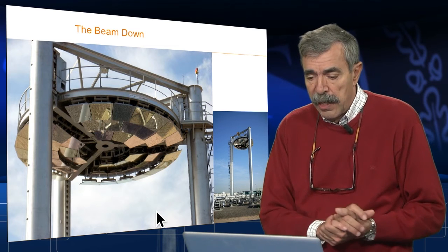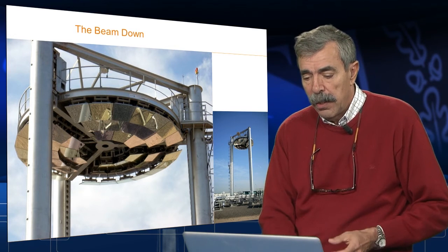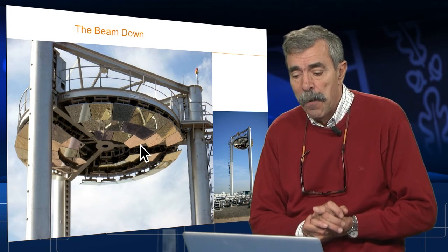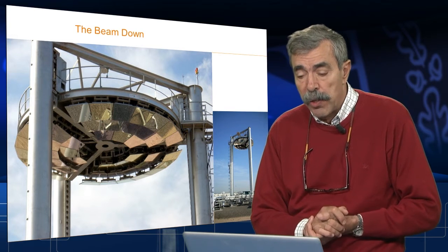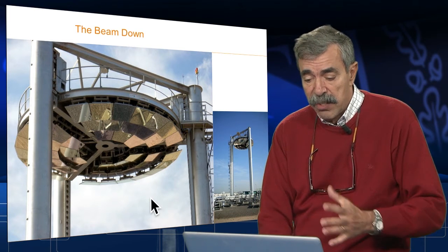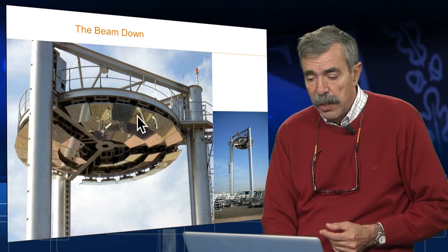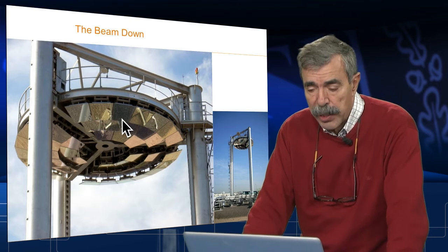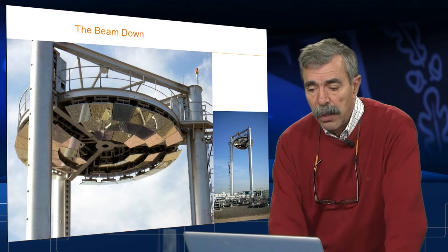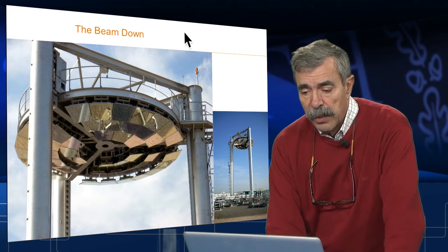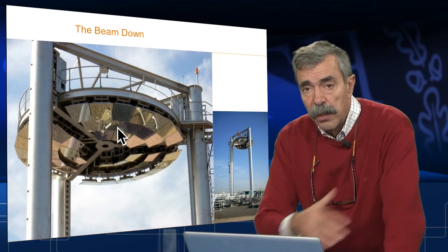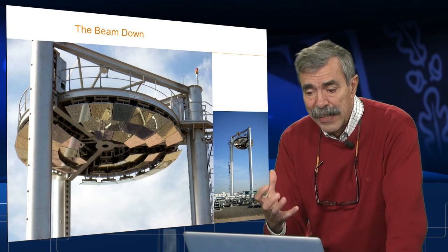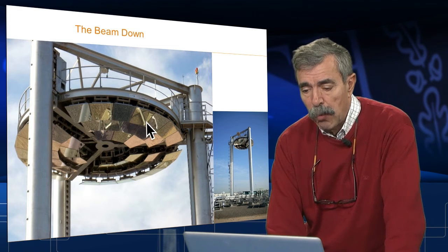Just to mention, in a small plant like Gemasolar, in the tower we are receiving like 140 megawatts of thermal energy. So imagine that in a similar plant with this configuration, if those mirrors have just a 5% reflectivity factor, you need to be evacuating something like 7 megawatts of heat. So that obviously is a big problem.